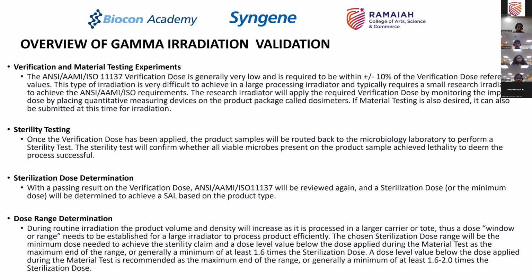Then after it is subjected to gamma irradiation, you send that same irradiated material to the same laboratory and evaluate it on the same parameters, to say that because of the gamma irradiation, your packaging has not deteriorated drastically. It may deteriorate slightly and may be stable. So again, stability studies will also have to get done over a period of time if there is deterioration. But you do material testing as well. So you have to do verification in material testing experiments once you decide the dose levels.